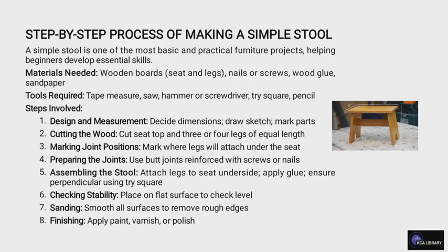And the steps include design and measurement, where you decide the dimensions, draw the sketch, and also mark the parts. Then you cut the wood, and then you mark the joint position where the legs will attach under the seat. You also prepare the joints, that is, use joints reinforced with screws or nails. The next is to assemble the stool. Attach the legs to the seat underside, apply glue and ensure they are perpendicular